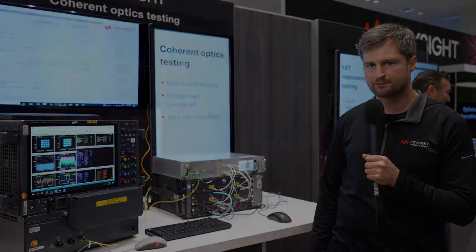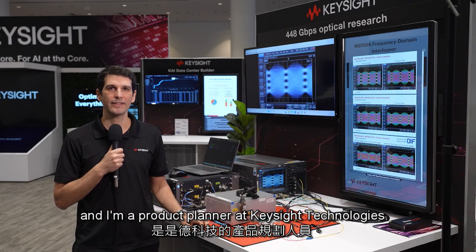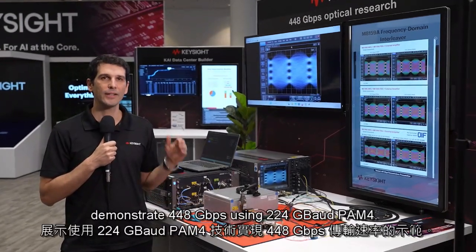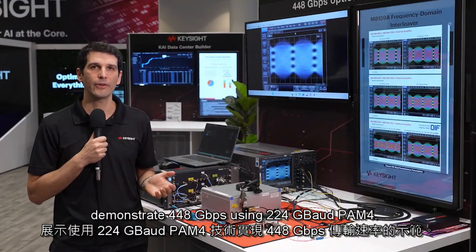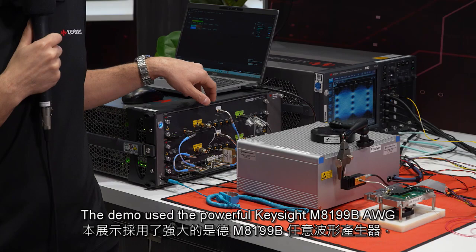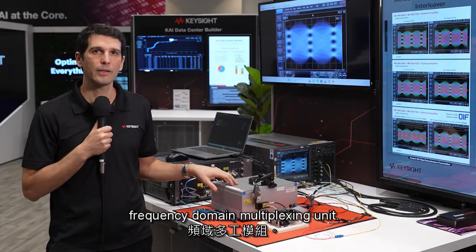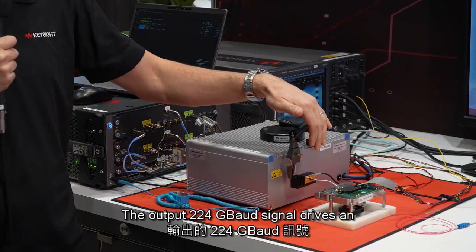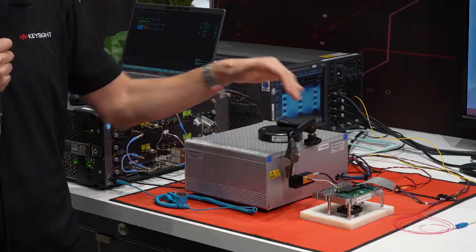Hi, my name is Fabio Pitala, and I'm a product planner at Keysight Technologies. Today, I'm excited to demonstrate 448 gigabit per second using 224 gigabaud PAM4. The demo used the powerful Keysight M8199B AWG linked through a high-performance frequency domain multiplexing unit. The output 224 gigabaud signal drives an externally modulated laser from Lumentum.